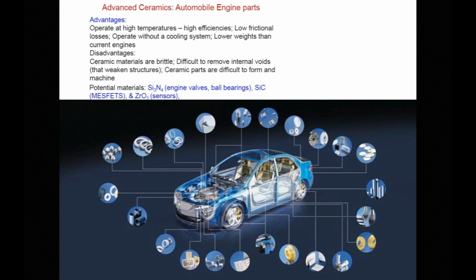However, one needs to again pay attention to disadvantages. Unlike metals that are ductile or polymers that are more processable under viscosified medium, ceramics are not. Ceramics are brittle materials. Their void spaces or internal voids are very hard to remove or can be controlled by looking at ways to change density.